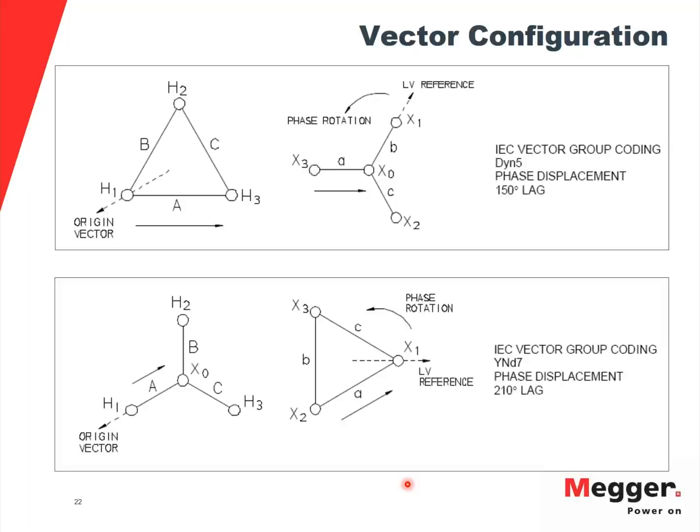So you're doing this make before break connection, and then we give you a good indicator, like if you saw our test results, we give you a pass or fail if we do that make before break connection. But if you do have an occurrence where actually that break happens first and you have an open circuit, we will discharge all that energy through the test set, through ground. Both the test set and the test technician will be protected there as well.